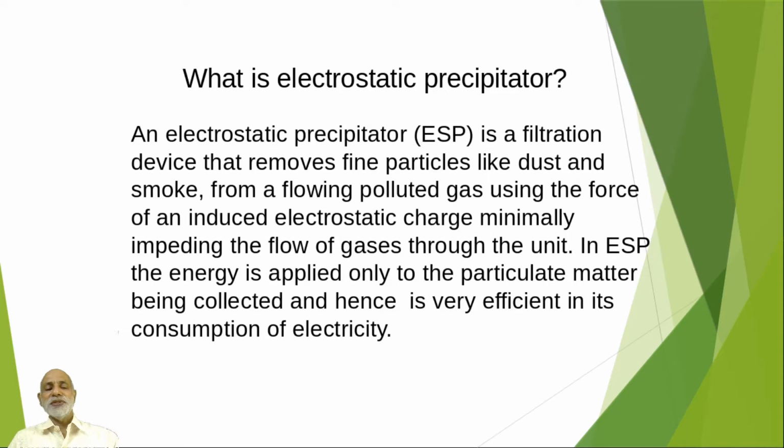And what is the technique? We are using the force of an induced electrostatic charge on flowing polluted gas. And now the flow of the gases is slightly impeded. Impeded means it is blocked slightly. The speed will be slightly minimized. So in an ESP, the electric energy is applied only to the particulate matter being collected, and that's a peculiarity of the ESP.